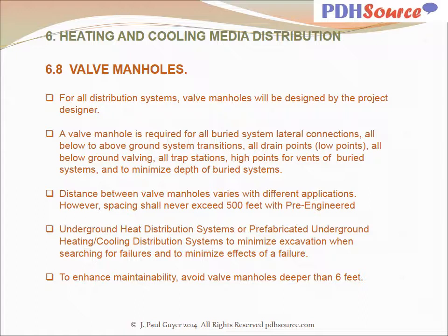Valve manholes are an important consideration. For all distribution systems, valve manholes shall be designed by the project designer. A valve manhole is required for all buried systems, lateral connections, all below to above ground system transitions, all drain points, low points, and all below ground valving, all trap stations, high points of vents of buried systems, and to minimize depth of buried systems.